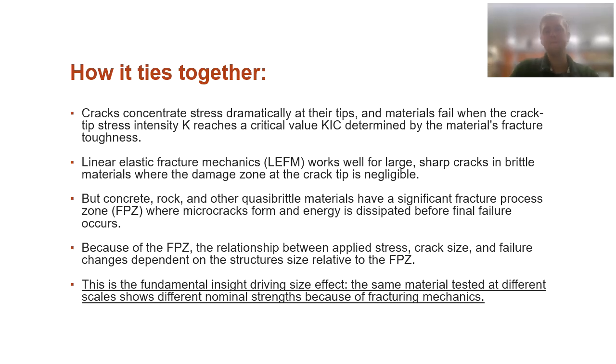One big takeaway: that LEFM works for these large structures, and we'll see this in Bazant's size effect in his graph as well, that LEFM applies to these large structures because the structure is so much bigger than the fracture process zone or the damage zone at that crack tip. It's almost negligible.